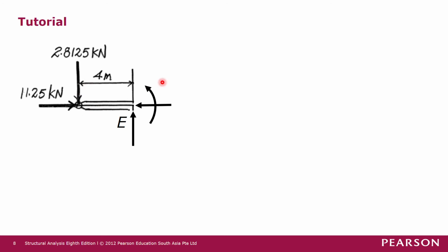And then we cut across joint E here, because joint E is a fixed joint, so we have 3 reactions. So we have Ey, we have Ex, and we also have ME. Okay, so all these are unknown forces, Ey, Ex, and ME. They are all unknown forces and moment. So as I mentioned, the direction of ME is also taken as the positive direction for the bending moment.